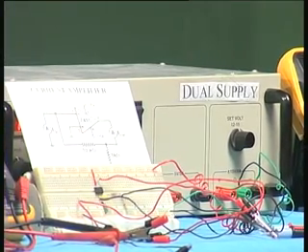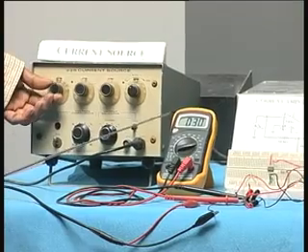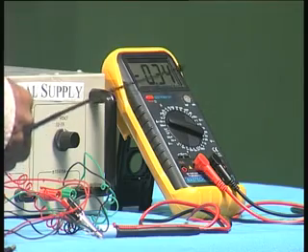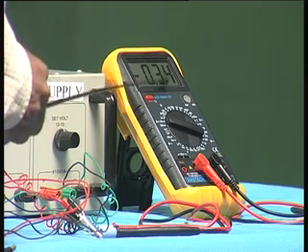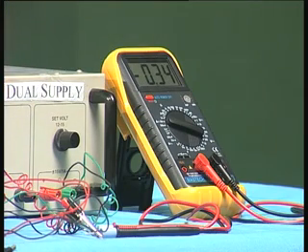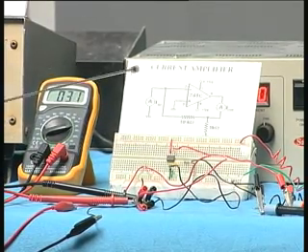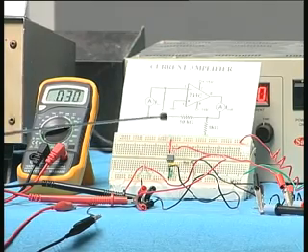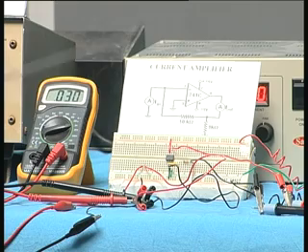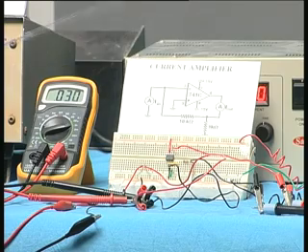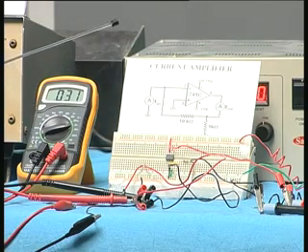If I now again increase the current to 30, you can see it is reading 30, and correspondingly at the output you have 0.34, that is 340 microamperes. So it is multiplied by 11 times, slightly more than 11 times. I already mentioned to you that the small variations you get are because the resistances are not exactly what we thought they should be. If you actually take the resistors, measure them using a multimeter and use those values in this calculation, you would find they match the corresponding readings here. But you can see that as I keep increasing the current, the output current also increases in a linear fashion, multiplied by the factor 11, because this is a current source.